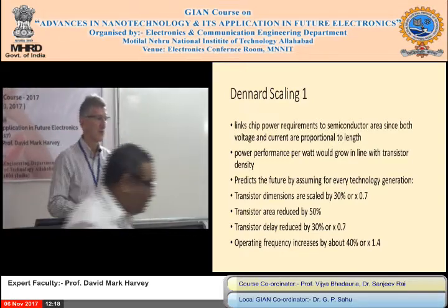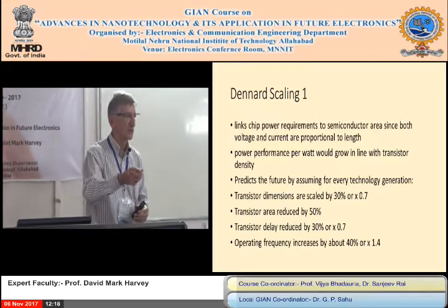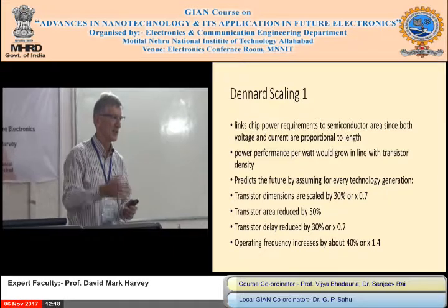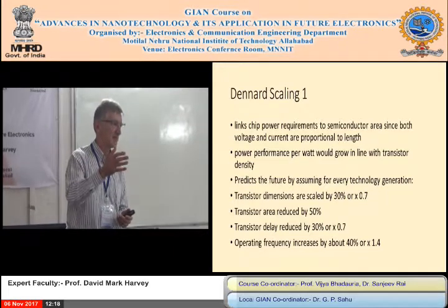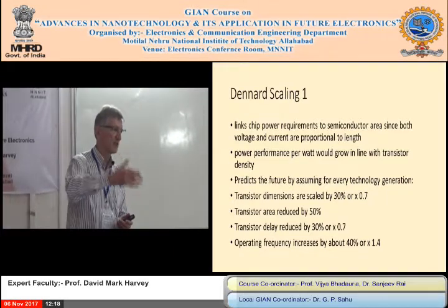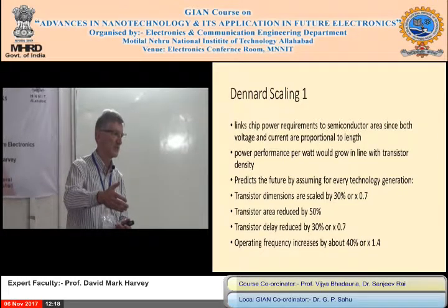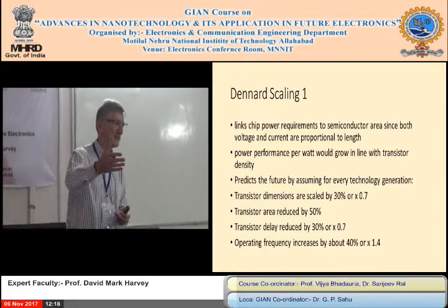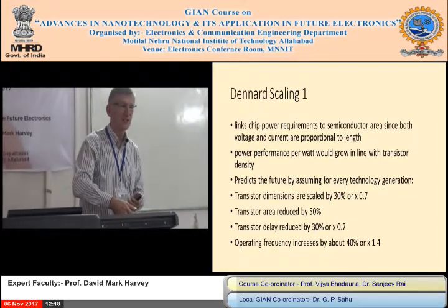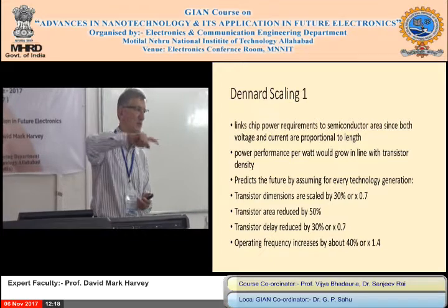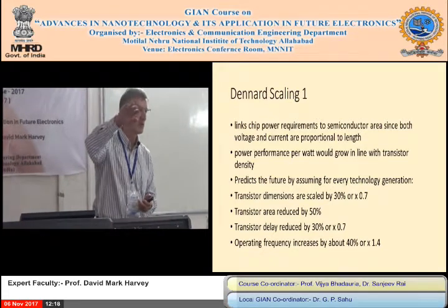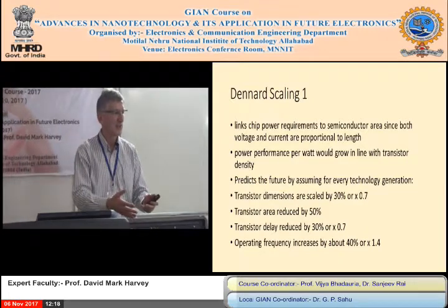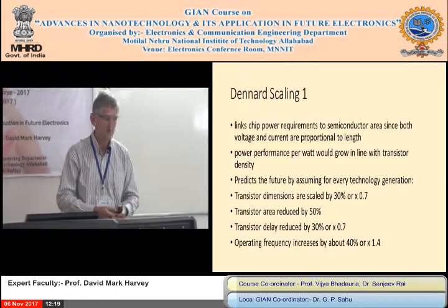Now, some of you may have done CMOS. What happens to CMOS if you turn up the operating frequency? Does the current go up or down? You've got a CMOS inverter, you clock it. If you turn the frequency up from, say, 10 megahertz to 20 megahertz, what will the current do? Go up or down? What do you think if you speed it up? It's going to go up, I'll tell you. It just about goes up as a straight line. So as you double the frequency, the power will go up. So by making the transistor smaller, taking less current, that's the double gain.